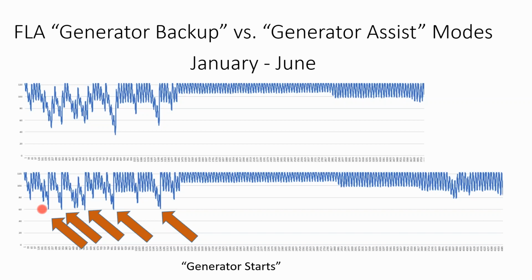Now, when you do a flooded lead acid battery, it's also good to have a generator there just for battery maintenance. That maintenance cycle, when you're cycling and using your batteries, might occur every 2 weeks. If you're not really using your batteries, the maintenance cycle might only be once a month.